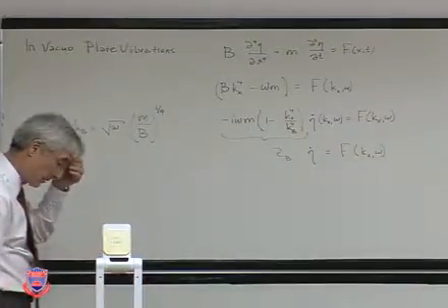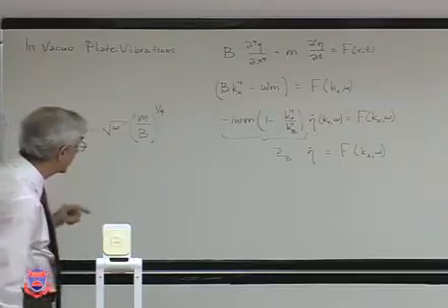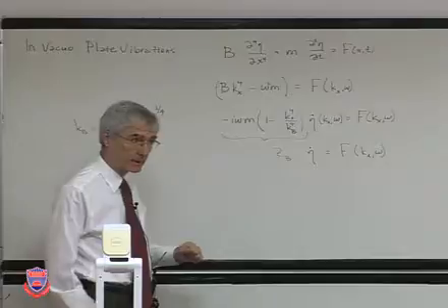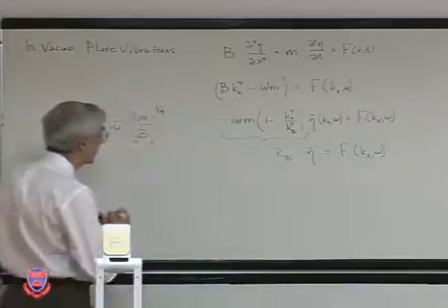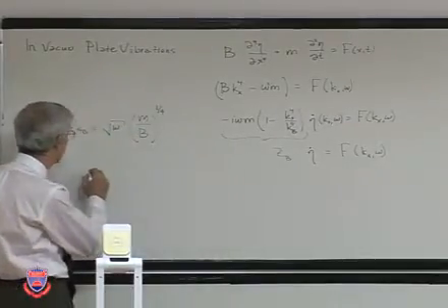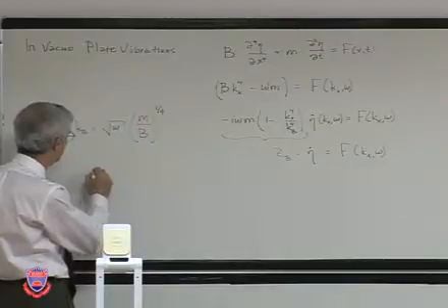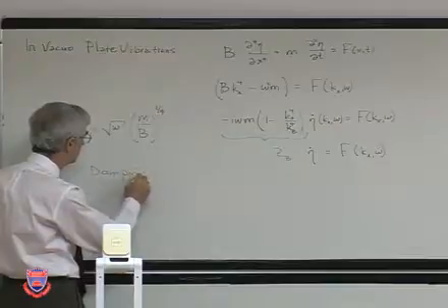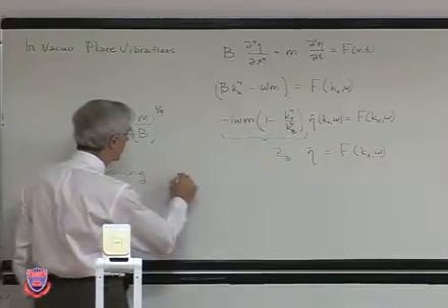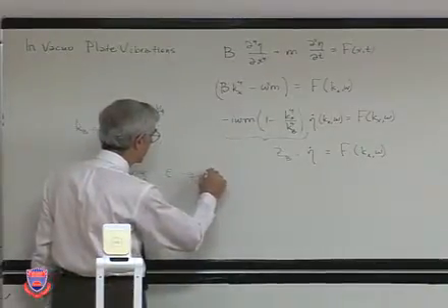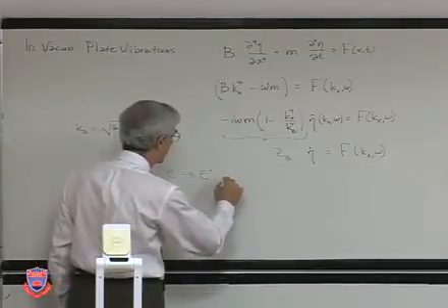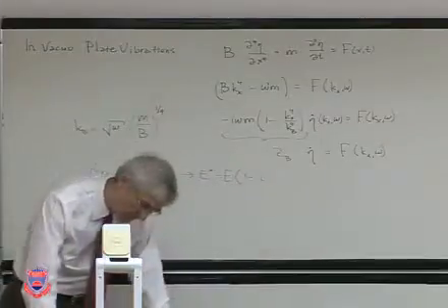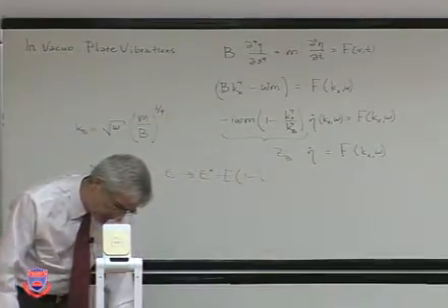Now there were a couple of things that we did. One is what happens to the impedance if you have damping in it. This one does not have any damping, and we said for damping, we write Young's modulus as a complex quantity and define it with a loss factor, delta.